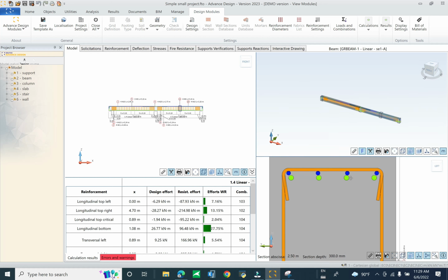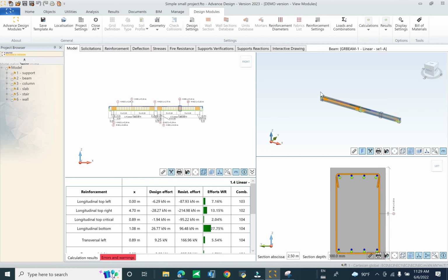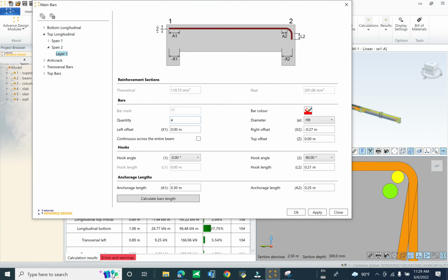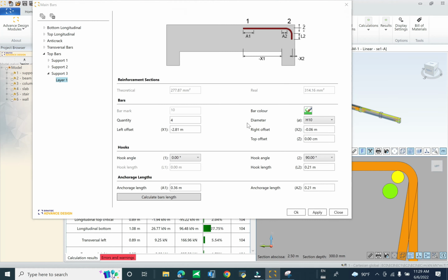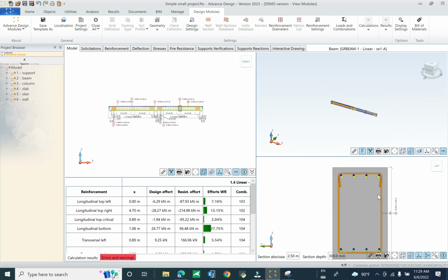Now you see the diameter of rebar, because you do not fit the diameter rebar, so they use between the larger and smaller diameter rebar. You can click on this one and double click on it. It uses diameter 8, and this one uses diameter 10. In the case you don't want to use rebar in different diameters, you can switch in the option rebar.